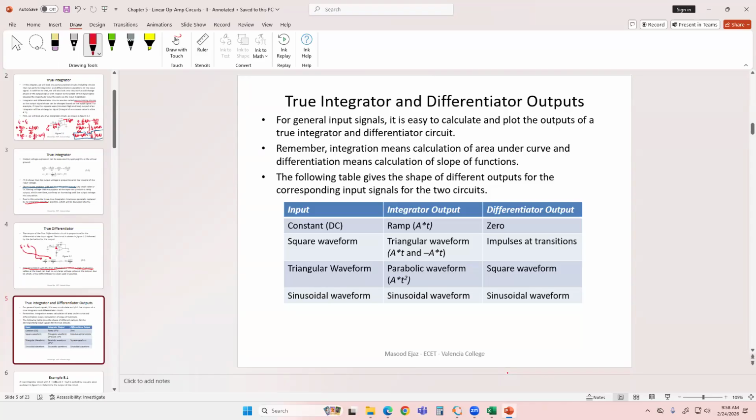So let's say your square wave, of course, all the practical square waves cannot go instantaneously from 0 to 1 or 1 to 0. For practice, it is impossible, because it will always take some time for any equipment to go from a high level to low level. Very small amount of time, but nevertheless, there is a time that it is going to take, which we call rise time, as we discussed, right? In the last chapter, we discussed rise time.